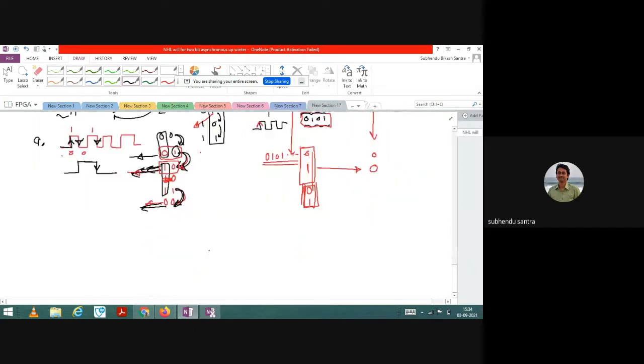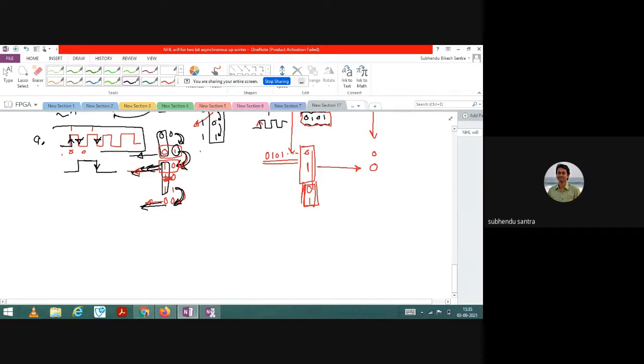So you see the problem of the asynchronous way of writing the code. Okay, the problem is first this variable or intermediate variable you have to take, and based on that where there is a toggling, that you have to check, then you can write. Again, if you have more number of flip-flop, then this will be the process, next process, and based on that the next output will depend. So there are a lot of propagation delay, and not only the propagation delay, but also you see the timing. Okay, initial clock, if your initial clock is this, so after that the frequency actually reduces, again the intermediate frequency it reduces, and finally when you have more number of flip-flop, the frequency actually reduces. Okay, so this is the problem of writing the asynchronous way of writing the code.